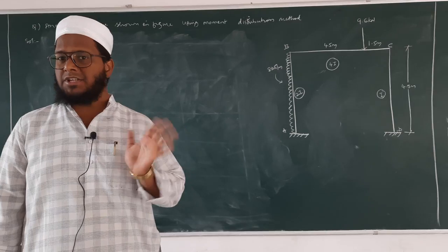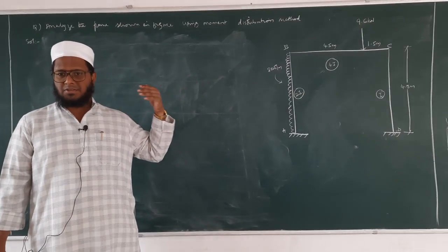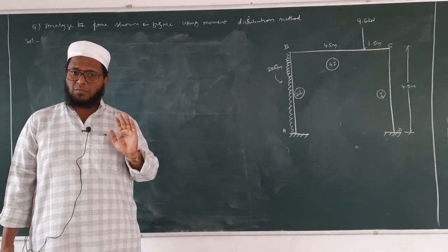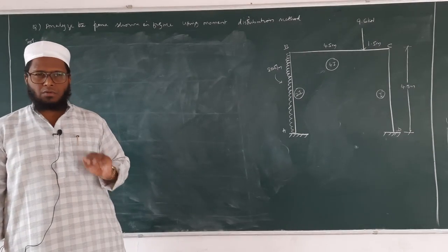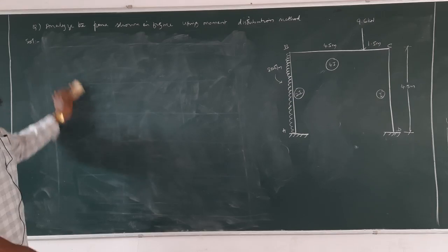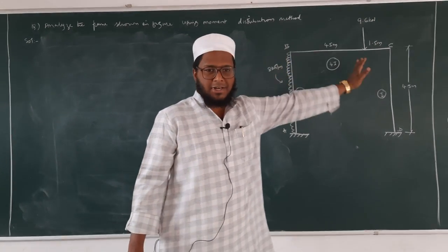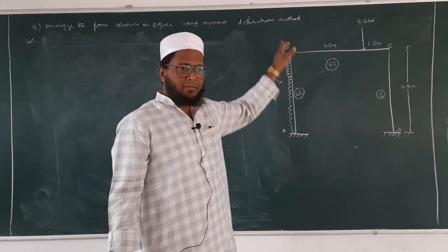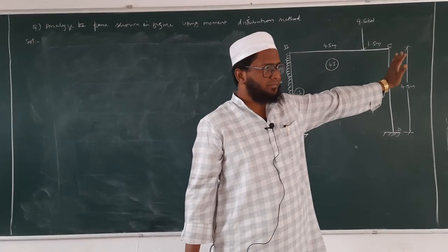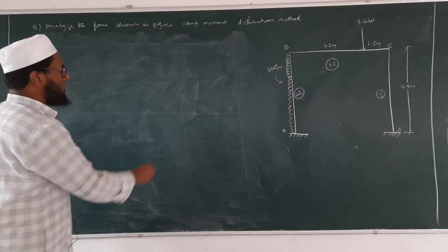We have not finished our problem so far. Okay, why? Because that is entirely sway moments or non-sway moments, isn't it? Now we have to consider sway moments. Okay, before that, you see here. If you see the frame carefully, the entire frame is trying to get pushed towards right side, isn't it? This frame, we have a horizontal loading, right? So our frame is trying to get deflected in which direction? Right direction, isn't it?